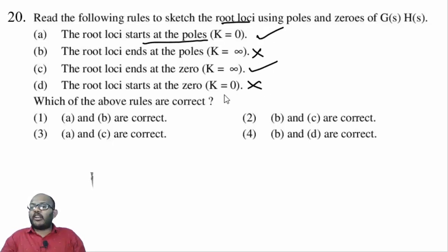If I am talking about inverse root locus, it will be starting at 0 and terminating at pole. In the case of root locus, you will be varying only one parameter, in most cases gain. But in the case of root contour, you are going to vary multiple parameters. Keeping all of the other parameters constant, you vary a single parameter and then solve. It is similar to the superposition theorem. So, statements A and C are correct, which is option 3.